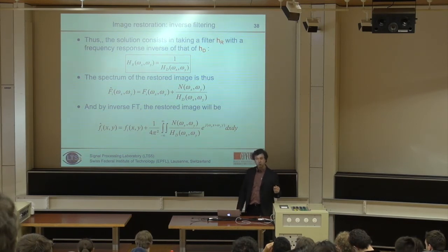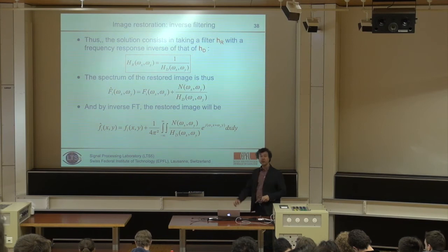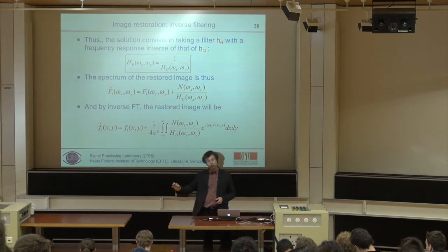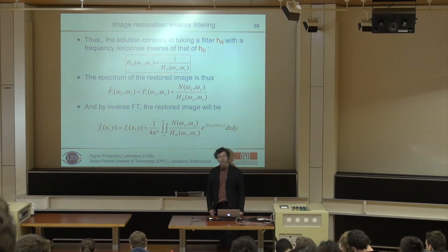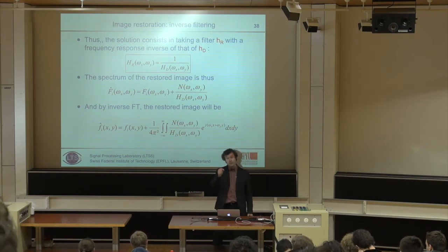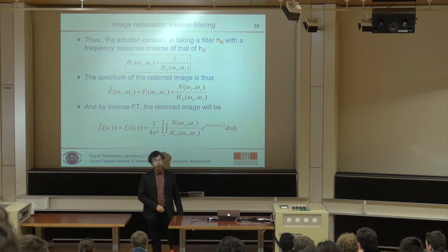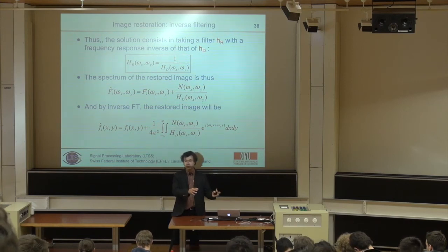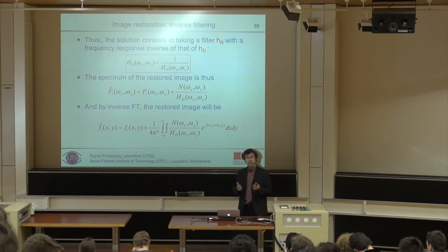I might ask you that also when we will meet one day or another. It's called inverse filter because the Fourier transform of the restoration filter is the inverse of the Fourier transform of the degradation filter. If you tell me it's called inverse filter because the filter is the inverse, it doesn't mean anything. The filter is not the inverse. The Fourier transform of the impulse response of the filter is the inverse of the Fourier transform of the impulse response of the degradation filter. Or the frequency response of the degradation filter is the inverse of the frequency response of the restoration filter, and vice versa. So let's be precise. It's called inverse filters because in the Fourier domain, one is the inverse of the other.